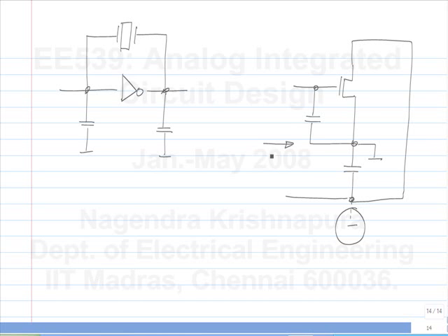Because this offers a negative real part, I can connect a crystal here. Again, I remind you that this doesn't have the biasing arrangement that is shown. Once you put the biasing arrangement, it will become complete. So if you put the crystal here, it becomes a crystal oscillator.